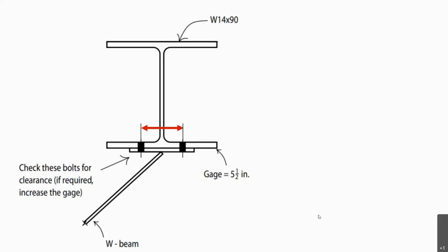It satisfies minimum edge distances, so the spacing from the center of the bolt to the edge of the column, and necessary spacing requirements for the bolts. It also provides spacing for entering or tightening clearances and avoids the chamfer of the column web.